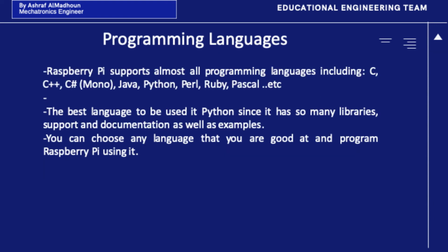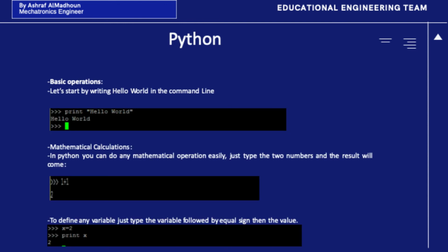The GPIO communication protocols and programming languages. Now, the Raspberry Pi supports 4 communication protocols. We have the I2C, the SPI, the UART, and the OneWire. And these protocols work on the same pins, so you can program pins to be input or output or communication protocol.